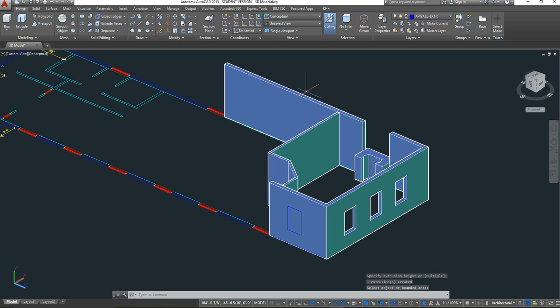Okay, and now I'm going to go ahead and escape out of this tool, and I'm going to make sure to go back to my world coordinates just to make sure I don't mess anything up. So I'm going to go back, I'm in my home, I'm going to go to coordinates, and I'm going to change it back to world. Again, that's just going to place my cube back upright and allow me to pivot around without any issues.